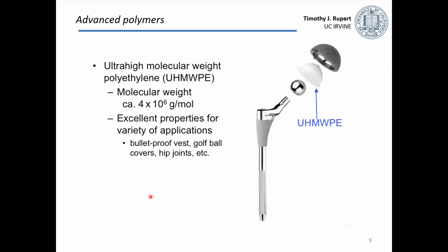In this last case, a foam structure might be useful if you want to have a really low density material. One thing I want to point out is those early examples I gave were sort of low tech uses. So, piping in your kitchen, bags and lawn chairs. But these same polymers can be used for advanced applications too. So I gave you the example of the little plastic bag for polyethylene. Now, if you make a different type, and we'll talk about what exactly this means, it's ultra high molecular weight polyethylene. This is what's used as the sort of replacement for your hip joint.